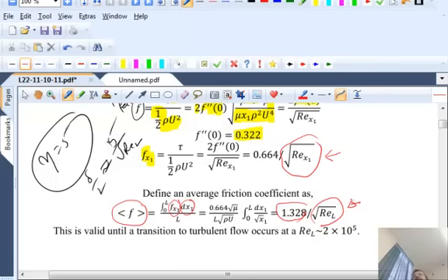So, like the local Reynolds number is larger than 2000. Good question. We are going to discuss that again a little later. But the 2000 number is only valid for pipe flow, circular pipe flow. So even if you have a rectangular duct, the transition occurs at a critical Reynolds number, but it is not 2100. It may be a different number. Okay, now, yeah, go ahead.